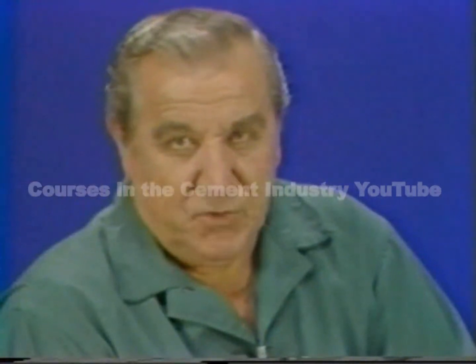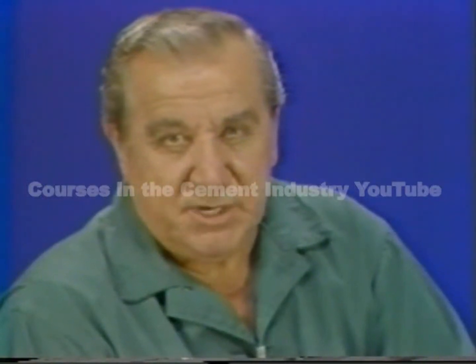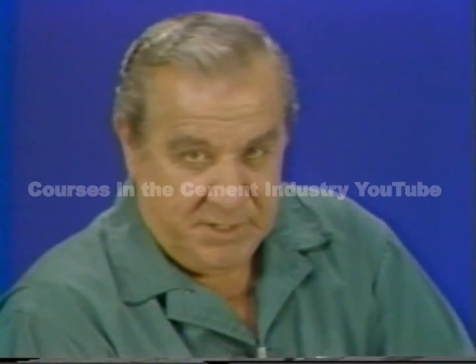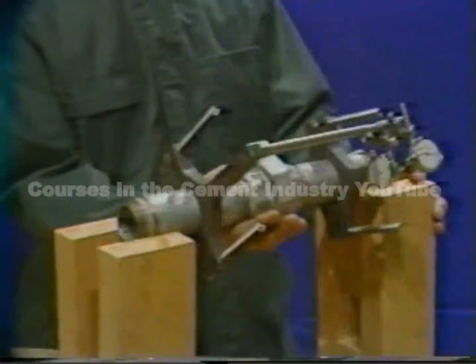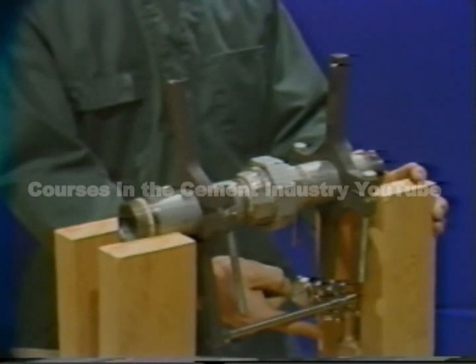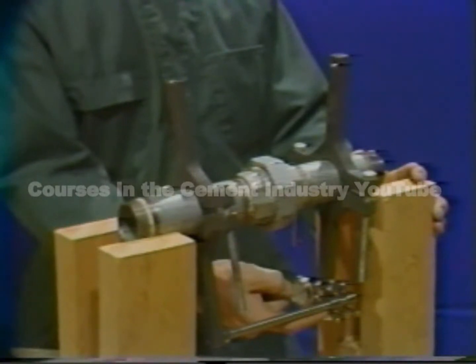Now, before you use the dials and brackets in whatever way you mount them, you should determine how much bracket sag you'll have. What's bracket sag? Let's look at the mock-up and I'll show you. Because the dial indicators are mounted on the end of the suspended rod, their weight will cause the rod to bend or sag a small amount. Even though it may only be a few thousandths of an inch, you should measure it so you can compensate for your readings during the alignment job.